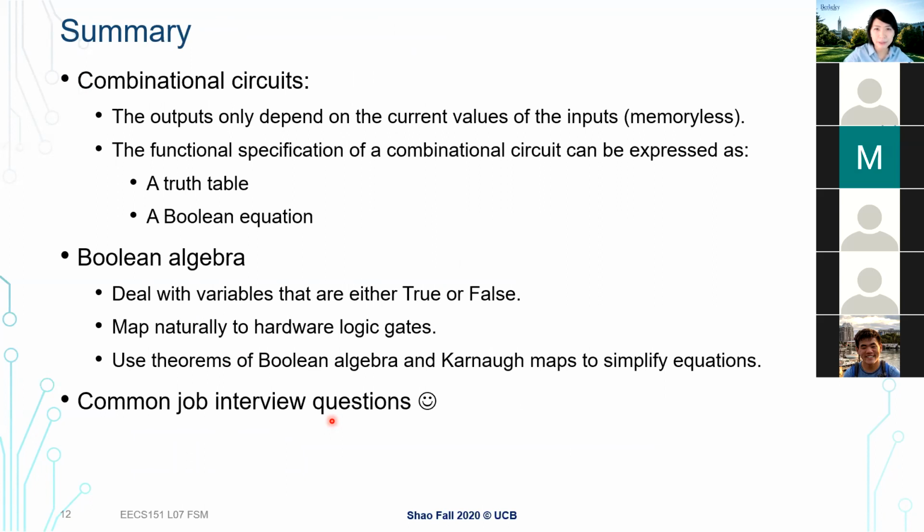And we have different representations to express logic. We started with a truth table, and we talked about how it's very useful. It's a unique representation, but it can also be tedious to write down all the combinations. And then we talked about how we can use Boolean algebra to express the Boolean functions or combinational functions. And then we can also use Boolean algebra theorems to simplify the logic. And alternatively, instead of using Boolean algebra theorems, again, the same fundamentals, we can use Karnaugh map, which is a more visual way to see the adjacency and apply the Boolean theorem directly.